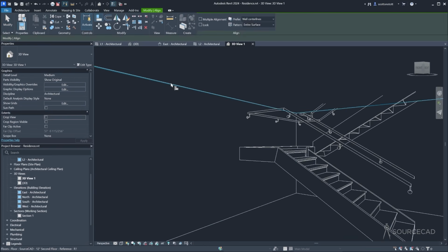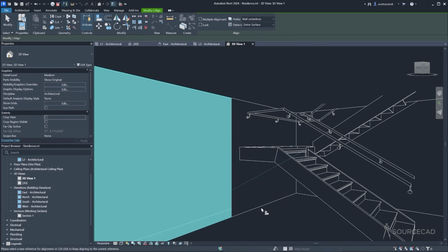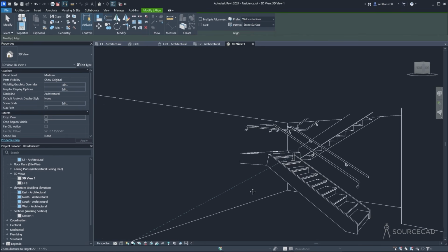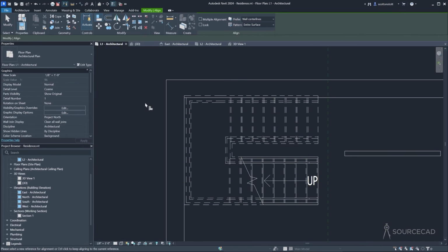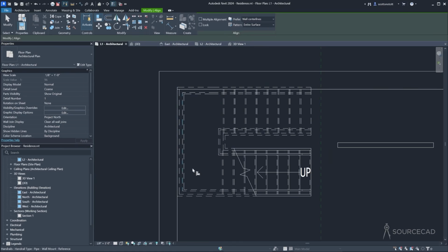All right. You can use align, click on the wall, and then I want to get the back side of the stair. So I'm going to press the tab key until I get that, and I can click on that, and that should line it up. And I think it did, but let's look at it in level 1. Yeah, it seems like it did. This dashed line is right on the wall. So evidently that dashed line is the border of the stair.